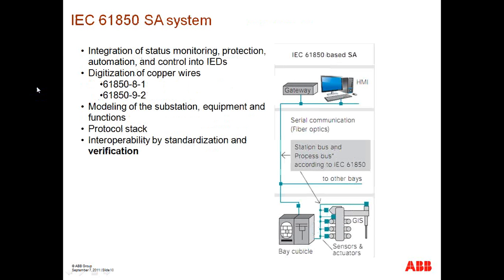Now when we move to what's envisioned by IEC 61850, we have a couple of changes. Number one, instead of utilizing proprietary protocols, we're using IEC 61850-1 so that protection relays or IEDs can share their status points over to a data concentrator. The second component of this architecture that's different from the prior slide is that now we have the process bus.